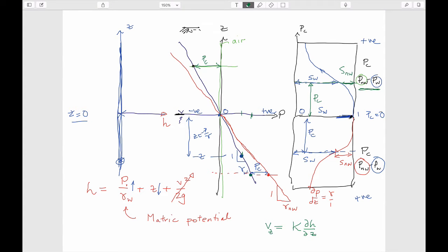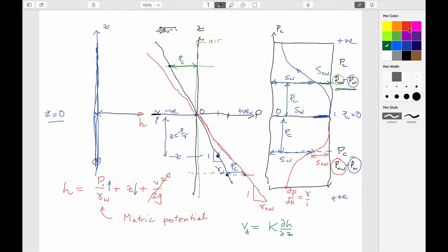The head, I guess, at this point here, it's equal to this. And at this point here, it's equal to this. What's the change in head between those 2 points? 0. So by definition, this is 0. If this is 0, this is finite, the velocity can be 0. So it's the same as sitting in a swimming pool, for the same reasons. That if you're at the pressure gradient of the fluid at rest, then it really is at rest.